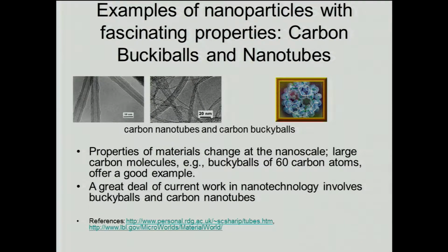You can use it as an extremely fine filtering mechanism. I said the size of the dust particles is 1000 nanometer, but those are big chunks of dust particles. There are dust particles everywhere. If you are looking at a fabrication facility, you have to keep the dust particles extremely small, because if one small bit of dust particle falls on top of it, there would be problems. So, how do you prevent very small dust particles from getting in? You might use this as a filter, so you can stop extremely small dust particles.